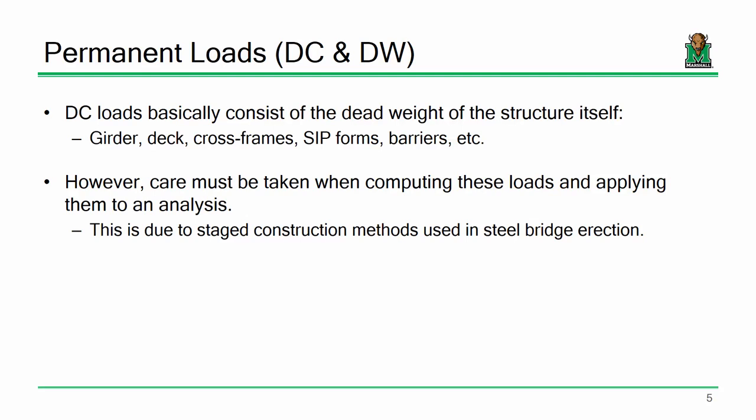But the big thing that you've got to pay a little bit of attention to is this whole concept of stage construction. Remember, I've brought this example up before, but you've got your bridge. Imagine that concept of stage construction. You set the beams, erect your cross frames, set your formwork down, lay your rebar out, start pouring your concrete. All those loads have to be supported by the steel beam by itself.